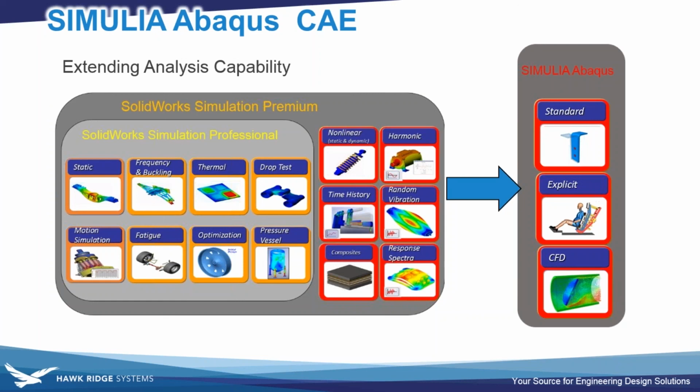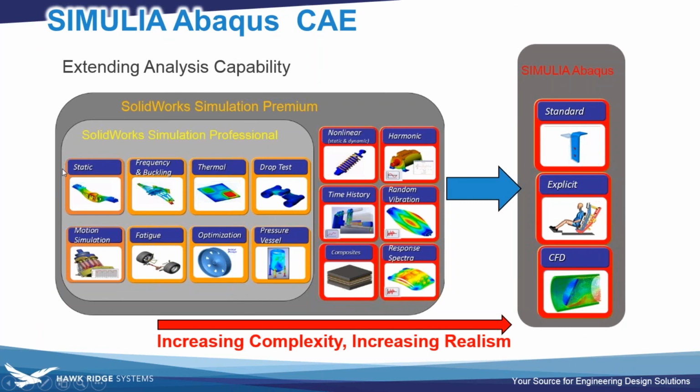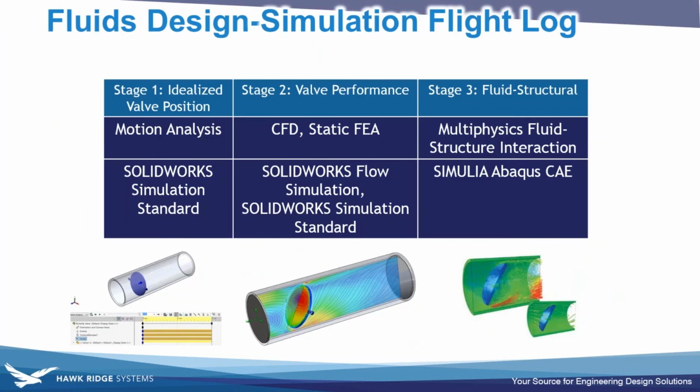Luckily, as I mentioned, we have pretty good experience with how to use SIMULIA Abaqus in conjunction with SOLIDWORKS, and so we can point you in the right direction of a good workflow, for example, using the SIMULIA SOLIDWORKS associativity. The associative interface is an add-in for SOLIDWORKS, which allows you to take your model and with one button you can export it directly into the Abaqus CAE interface without having to manually save out a file type or convert using some other format or resolving importing errors. So by using that associative interface, your SOLIDWORKS model will appear instantaneously in Abaqus CAE, and of course if you change the model in SOLIDWORKS you can update it with the same process.